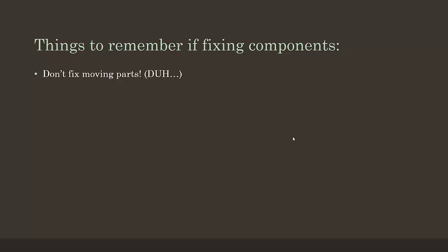It does shorten your rebuild time. In fact, what I'm skipping over is the rebuild of all the mates. So it definitely does that. It does not really do anything for your file size, because it's still storing the mates. It doesn't reduce your file size, but it does definitely reduce the rebuild time.